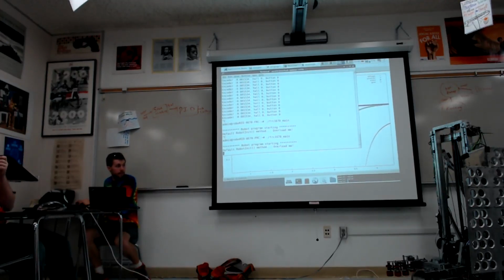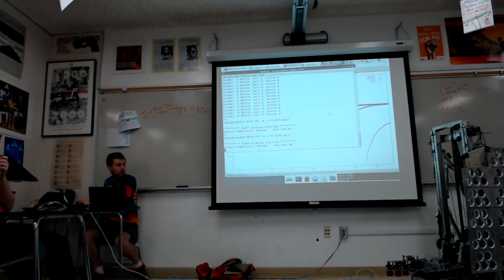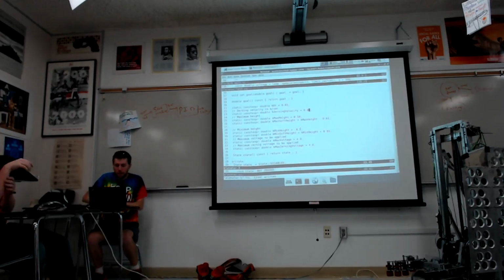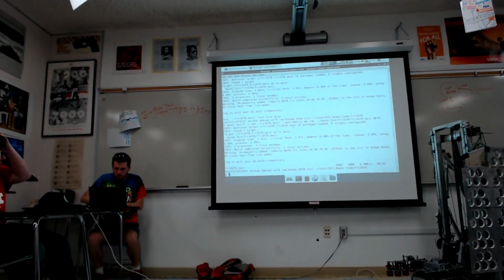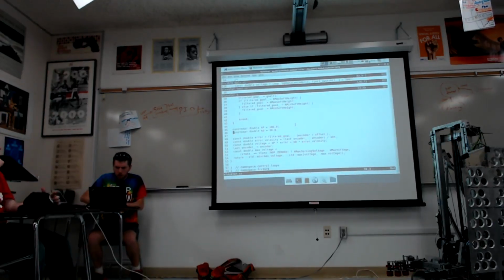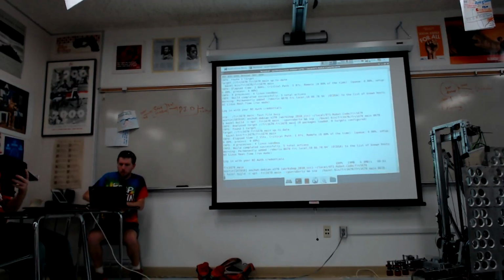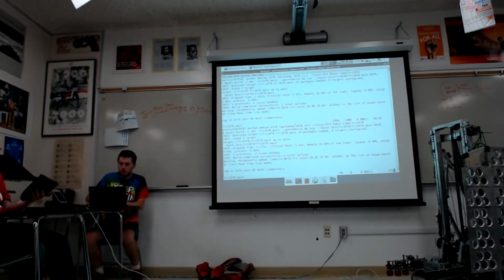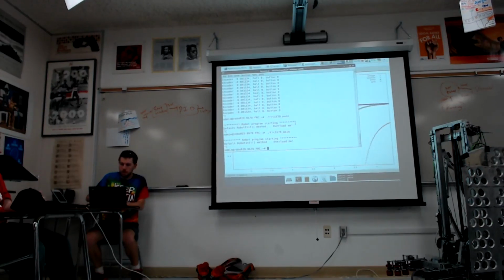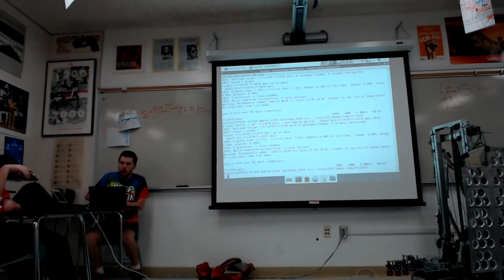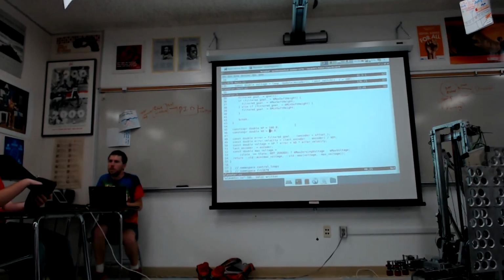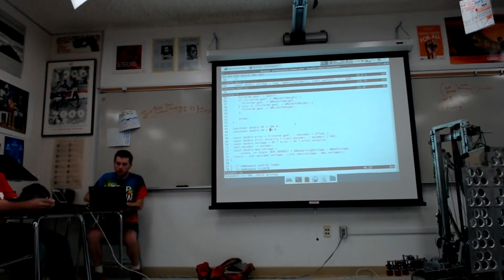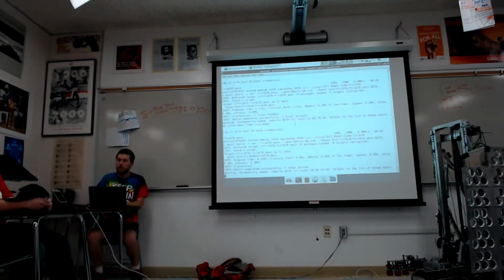Ready? Oh, I lowered the derivative constant. That's high frequency noise. It's very likely coming from the derivative, because it amplifies high frequencies. So we'll back that down. Looks like our simulation was a little too perfect.